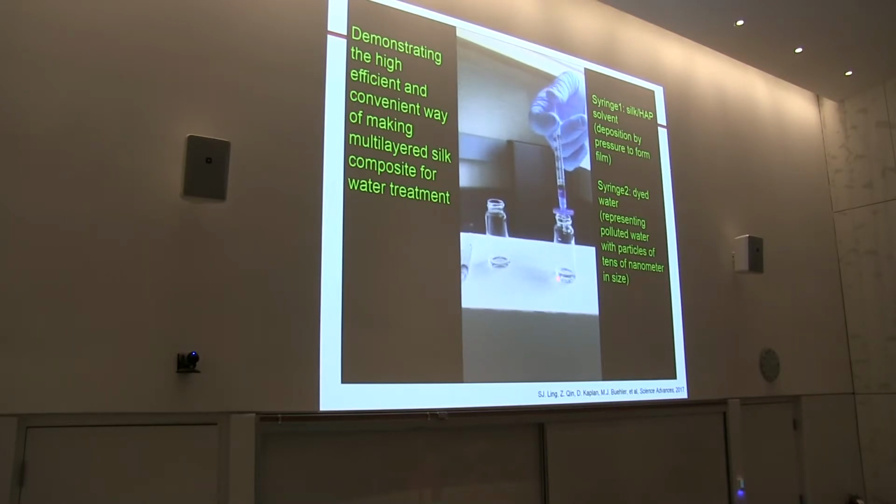So it actually ends up with just the water without those fluorescent dyes. The reason is that hydroxyapatite provides good porosity to the material, but the silk provides good strength to connect the hydroxyapatite in the membrane. That allowed me to apply such a high force or pressure to force the solvent through. And then the physical pore size in the hydroxyapatite, as well as the large surface area, help to block those nanoparticles from reaching the other side of the membrane.